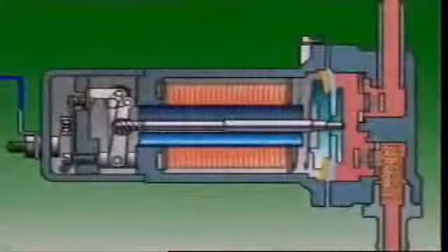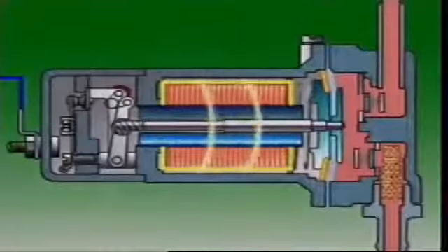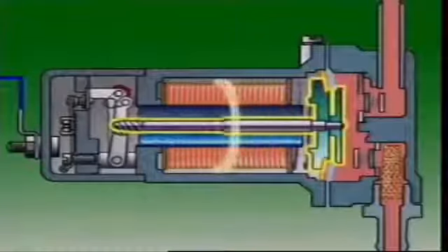Carburetor systems can also use electric fuel pumps. Most of these pumps are located outside the tank, though some are inside the tank. One widely used pump is the diaphragm type. It has an electrical section and a mechanical section.